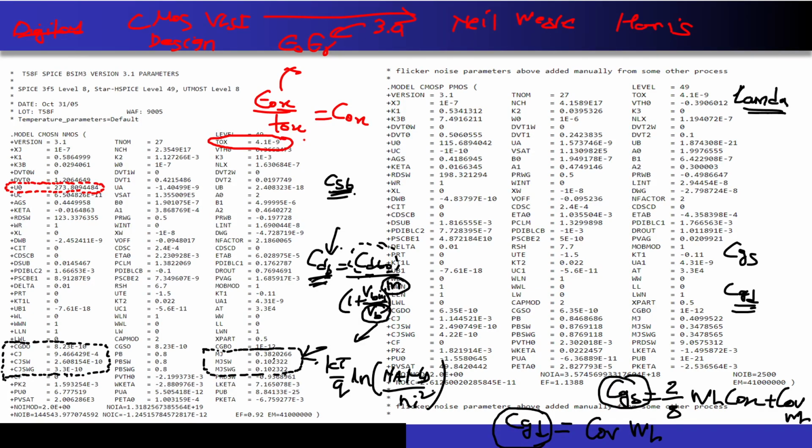So now, if we had asked you to calculate this by yourself, this would have become a very lengthy numerical, right? Because you are literally going into the structure of the MOSFET. From there on, you got the CdB naught. From there, you got the CdB. From here, you got the CSB as well. You had to calculate the built-in potential by yourself only, correct? By given dopant concentration. Then you have to calculate CGS, CGD. And then once you know this, correct?